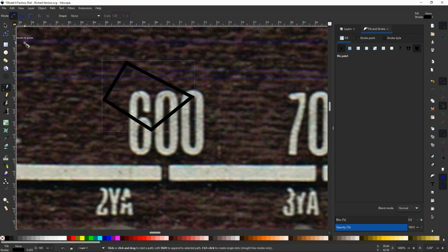If it doesn't, what you can do is highlight here, because what you'll have is two nodes, one on top of the other, and the tool we want, if I can remember which one it is, join selected end nodes. I think this one here, join selected nodes. The nodes are actually sitting on top of each other, so you just have to do that. In this case, they were already joined. You would see the two ends of the line sitting overlapped if they weren't joined,